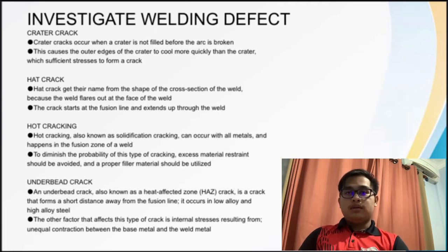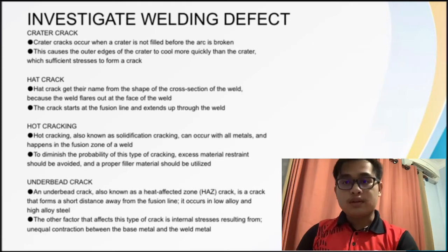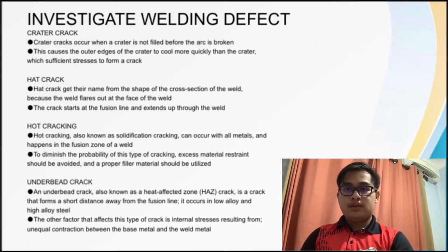Crater crack. Crater crack occurs when a crater is not filled before the arc is broken. This causes the outer edges of the crater to cool more quickly than the crater, which creates sufficient stresses to form a crack.